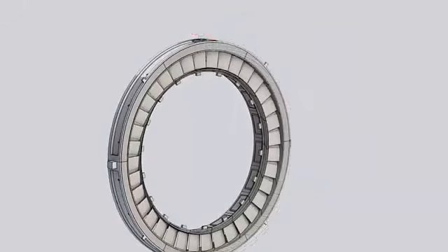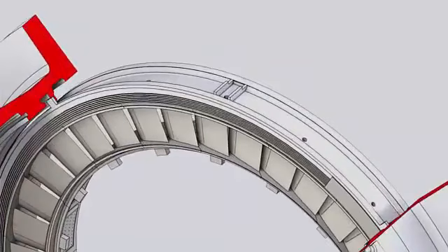The nozzle one assembly is prevented from moving forward by four lugs extruding from the outside diameter of the retaining ring at 45 degrees from vertical and horizontal center lines. These lugs fit in a groove machined on the turbine shell.